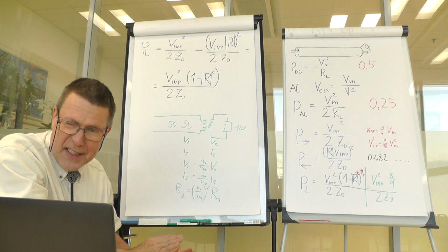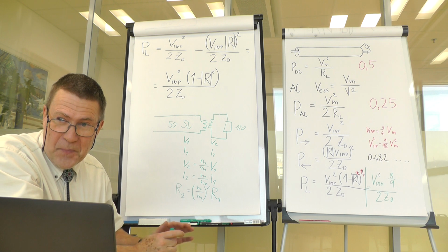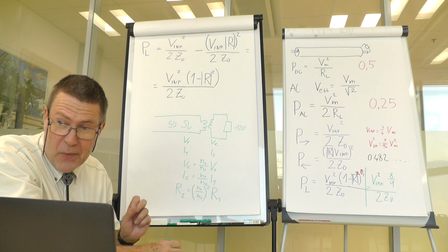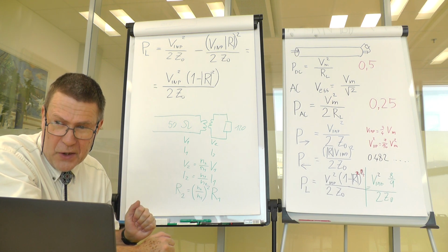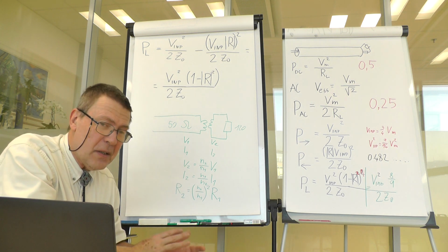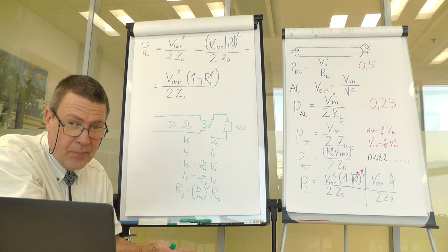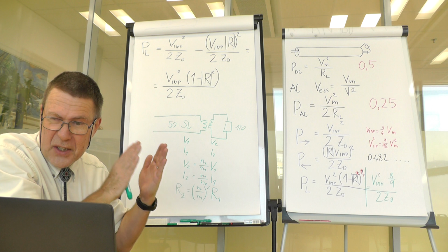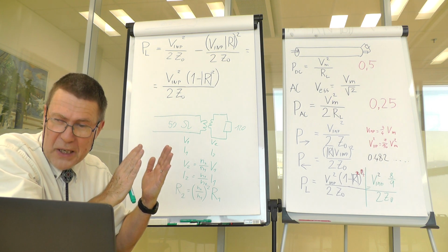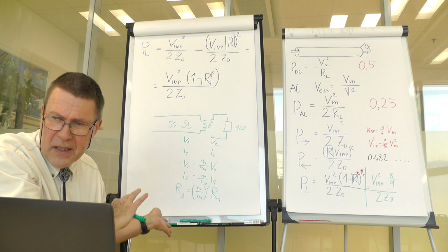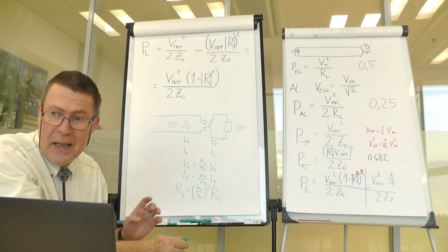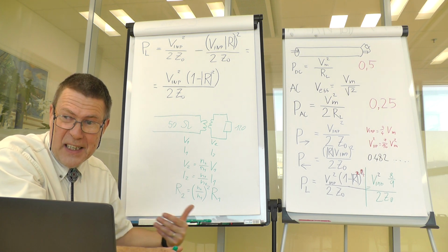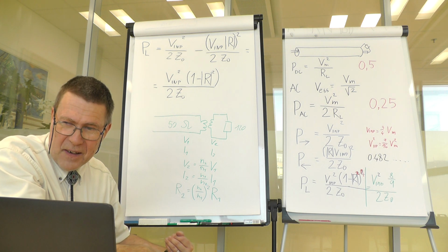So there are other techniques that I will describe only later. So yes, this is the most important part for a radio frequency engineer, impedance matching. That's very important. It's not that important for, let's say, construction of locomotives or heavy current, because the dimensions there are very small when compared to the wavelength. So then you just work with DC and AC. But at high frequencies, you still have to think about standing wave ratio and impedance matching.